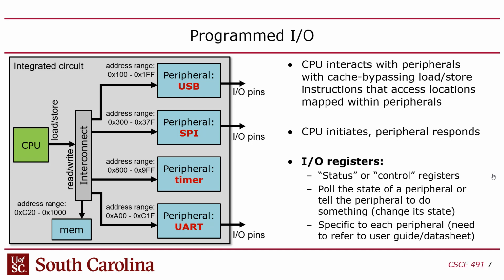And all of that is done through this programmed I/O, and every one of these modules has an address range. And I mentioned these are magic numbers. Magic numbers meaning they're immutable ranges of addresses that you just have to accept as a programmer. Now, if you got an FPGA, you're designing your own hardware, like we used to do in this class, you can change these numbers. But when you have an off-the-shelf chip like the ESP32, you've got to live with the numbers they give you. Okay? So you have to look. All of these come from the user manual. Which, by the way, if you've been on Dropbox, you'll see I've got a link to the technical reference manual for the chip, and so part of the reason you have to go to that technical reference manual is to look up these address ranges.